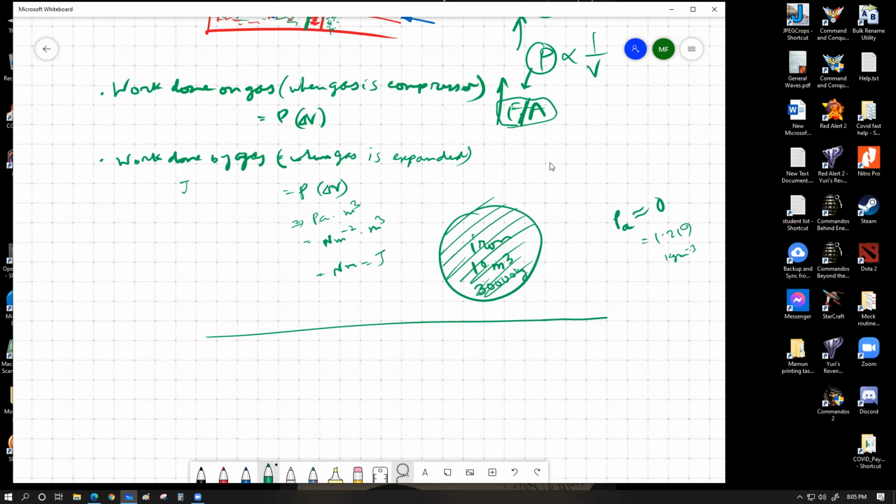Let's say whenever we're going to start to submerge this iron cube inside water, as more and more part of this iron sphere starts to enter under the water level, it is going to displace some amount of water equal to the volume of itself that is under the water level. So the amount of volume of iron that has submerged under the water, that same amount of volume of water has to be pushed out. The weight of that pushed out water amount will come as upthrust.